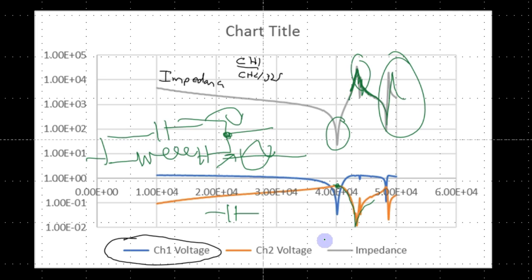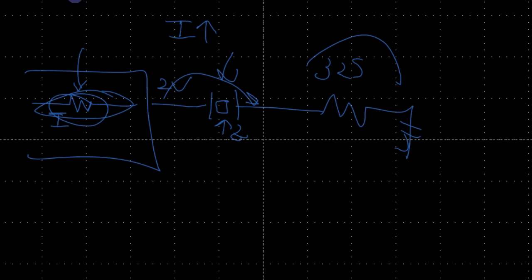One thing you may not have expected is how come this current, the orange, doesn't peak up like that. The reason the current doesn't peak up is because of the series resistance and the output impedance. When the current starts increasing, the voltage across the transducer starts decreasing because the voltage starts dropping over these parameters. So it sort of self-balances itself out. It balances itself, therefore the current is sort of maintained uniformly.